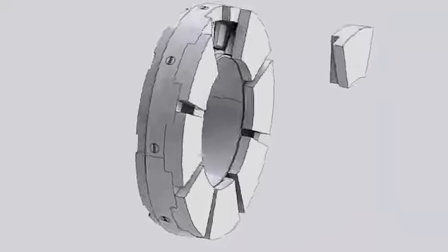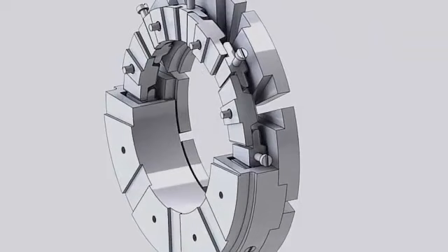The leveling plates are functionally small levers. They align the bearing pads with the thrust runner and equalize the load among the pads despite any possible slight misalignment of the shaft axis from the normal. The leveling plates are mounted on the base ring by dowels and screws, such that the plates are free to tilt on their fulcrums.